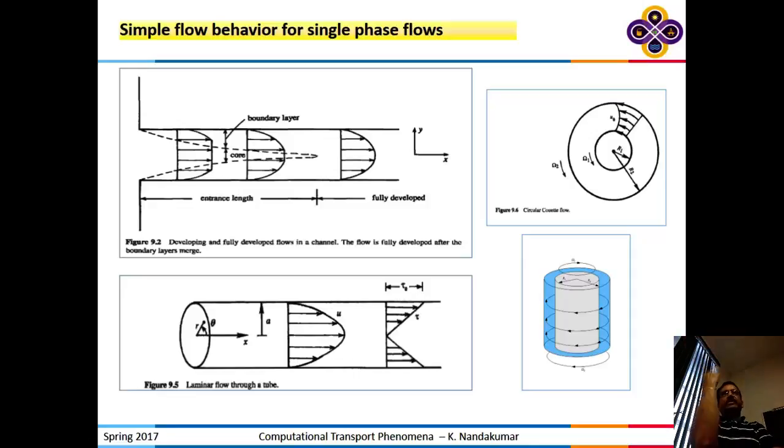And you are arguing that honey will develop quicker. And you are saying water will take longer, which is the same as saying honey will be shorter. Right? That is the right answer. If you remember from boundary layer theory, the boundary layer thickness grows as the square root of nu, the kinematic viscosity. Okay? So the larger the kinematic viscosity, the faster the growth. And if it grows to the center, it's done. Right? So the growth rate is essentially how fast it grows to the center.